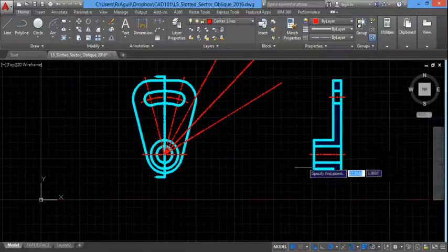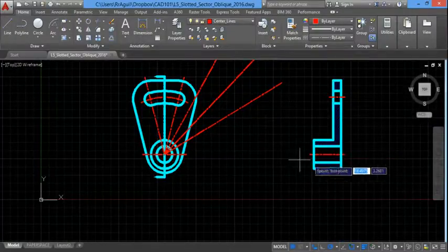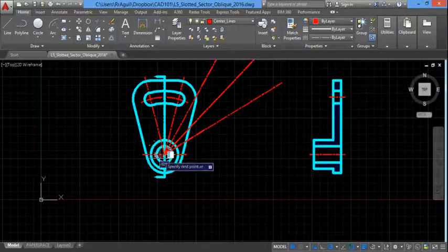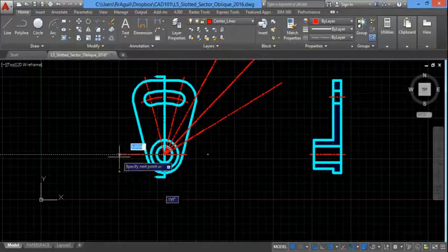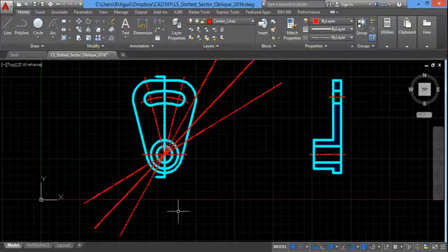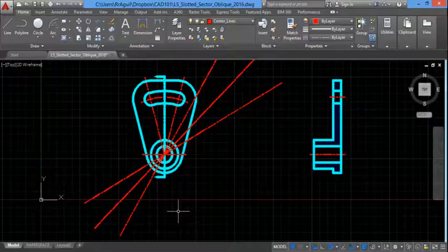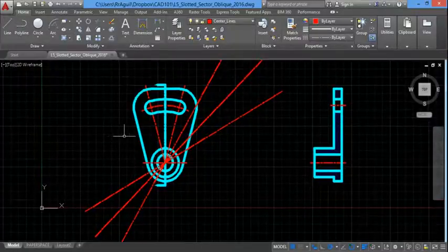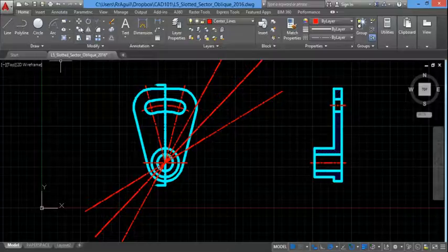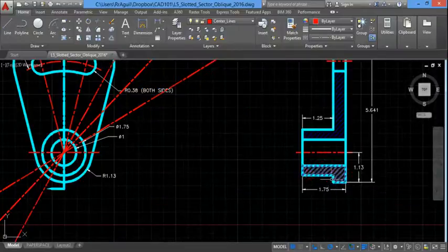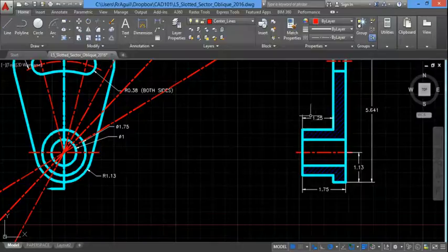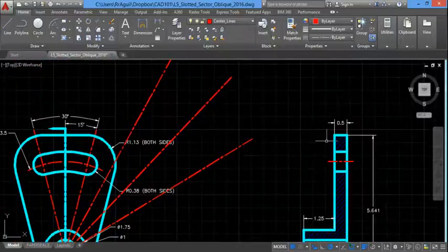The part has a cylindrical object that will extrude forward, so I'm going to project 30, 45, and 60 in this direction also. What I'm going to do is see which option is best by using the copy command and extruding along the length of these lines. The distance of the cylinder going forward is going to be 1.25, and the depth of the part going backwards will be 0.5.